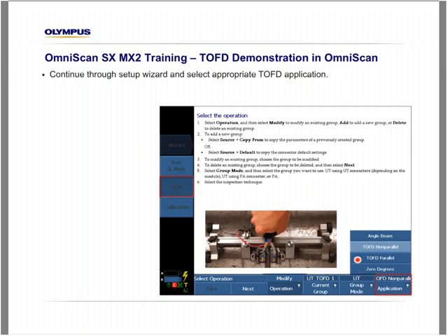The overwhelming majority and typical TOFD inspection we see here is a non-parallel, and what the non-parallel refers to is that the beam orientation is perpendicular to the weld scan axis as opposed to parallel. So our typical TOFD inspection you see here would be a non-parallel inspection.